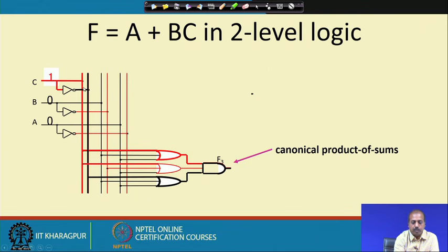this inverter output will be activated. So, the inverter has got some delay. Before the inverter delay was activated, this OR gate was remaining at 1. So, you are getting some output, but now after some time this inverter will be equal to 0. As a result, this OR gate value will become equal to 0. So, this F 3 will be equal to 0.